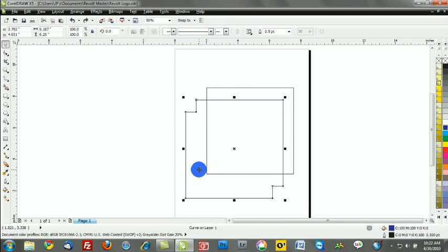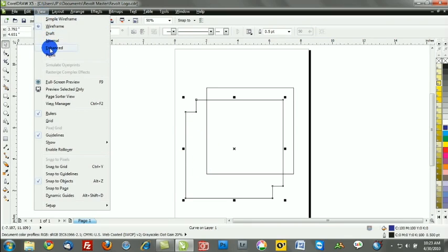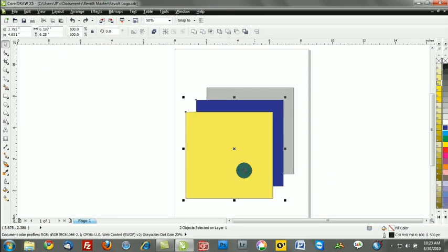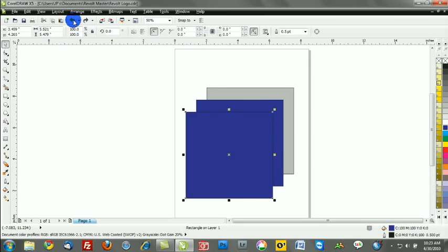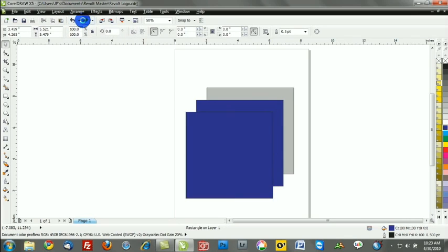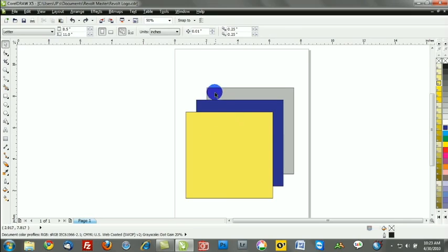It's a great way to take really complex objects and just blend them into one seamless path. Now if I go back to the enhanced mode, you can see how that's now transformed. So hit Control Z for the before, and we can use these little arrow keys, the undo and the redo button, to go back and forth. You'll see we have one solid object fused together versus two independent objects. So that's the weld command to fuse multiple objects together.